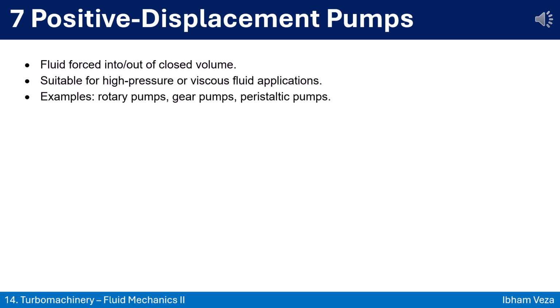This mechanism makes them ideal for applications where high pressure is required or where the fluid is highly viscous, such as in lubrication systems, chemical dosing, or food-grade pumping. Unlike centrifugal pumps, they don't rely on velocity but on displacement, hence the name.